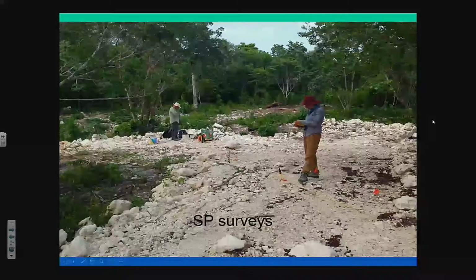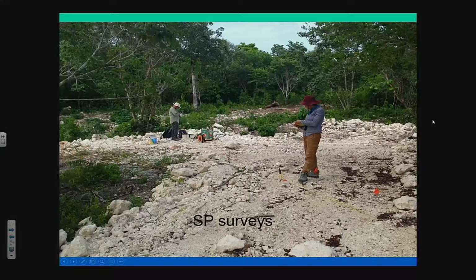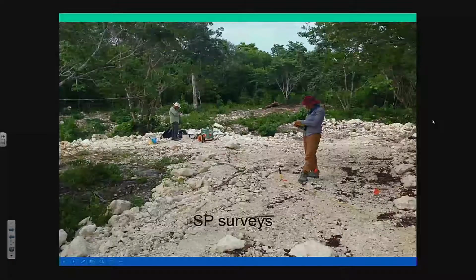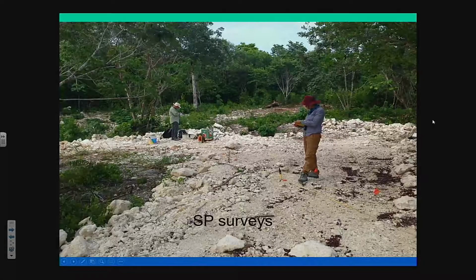And this is a survey we did a number of years ago. And here you can see part of the cenote over here. So you set up these special types of electrodes. They have ceramic tips on them. You fill it with copper sulfate solution. And then if you look very carefully back here, you'll see the instrument we use for the recording.